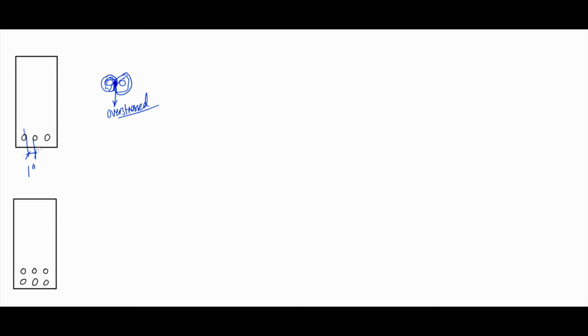Now, the cover from here to here also is specified. Sorry, when I say 1 inch, it's equivalent to 25 mm in the SI unit. Right, so when we go back again, the reinforcement, also the clear cover, or something called cover, is from the middle of the bar to here. We usually take it 2 to 3 inch.